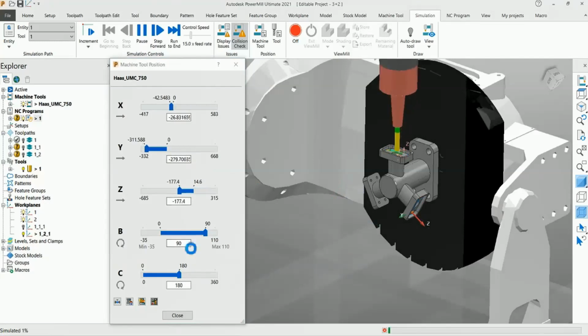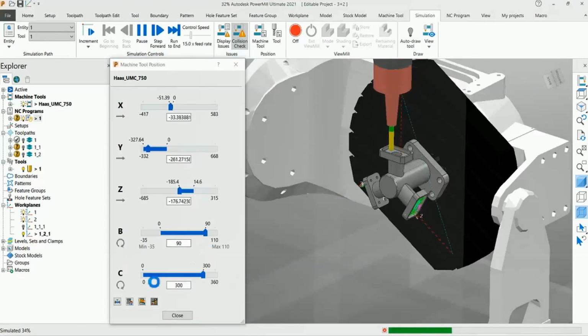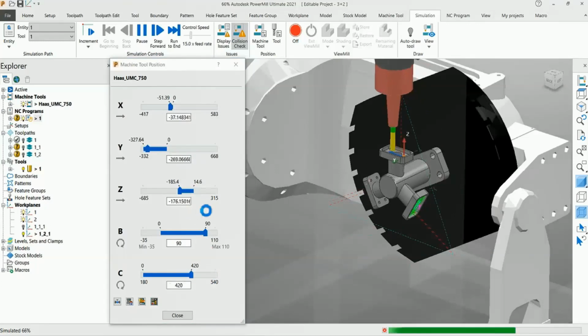You can see that two of the rotary axes are getting fixed or locked, and 3-axis machining is getting performed. Once it is completed with the depth, you can see that one of the axes is getting rotated. Here it is going to C axis 300 and it is making a 3-axis local roughing toolpath. Similarly, it will rotate to the other movements and complete all the 3 profiles here. So this is a perfect example of 3+2 machining, or we can simply call it positional milling.